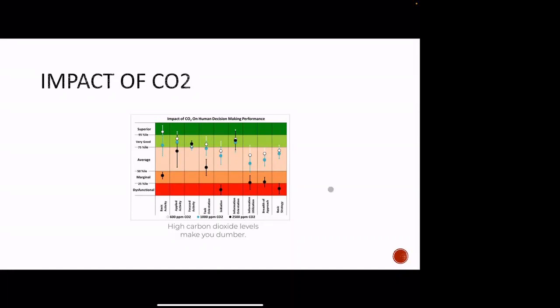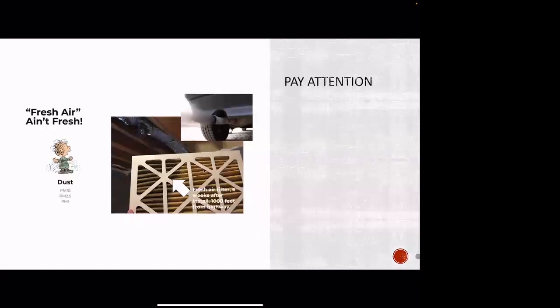So with everybody staying in their home with everything that's going on with COVID and everything, understanding carbon dioxide levels and that fresh air is very, very important. And just educating the clients is what we need to do. So we want to pay attention though. If we're installing ventilation, if we're installing that ERV or that mechanical damper, fresh air ain't always fresh. Depends on where you're pulling it from. Be careful, be aware, know how to install it properly.